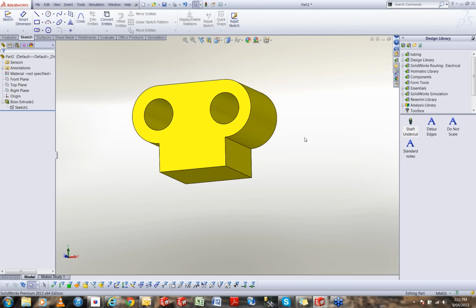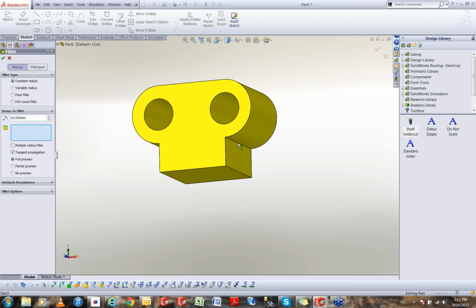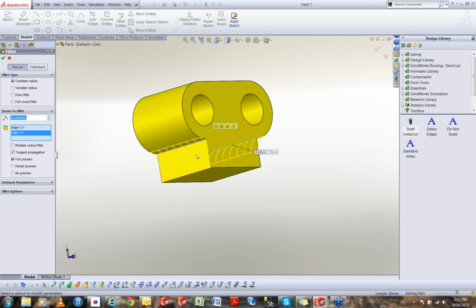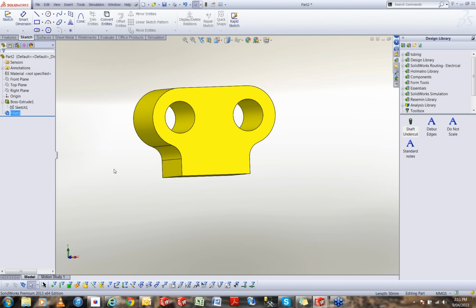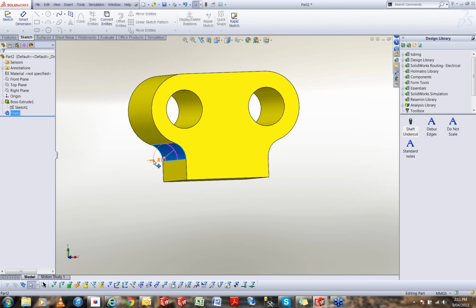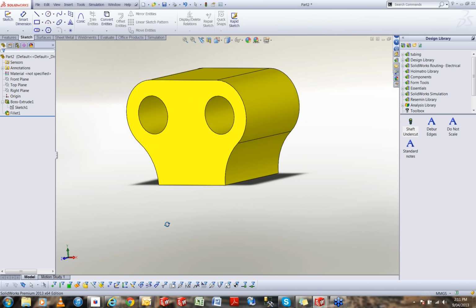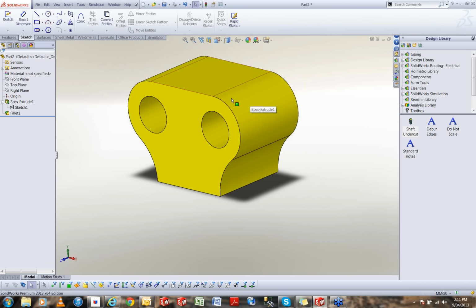So we've got a fairly sharp corner here where the circular face meets this flat face. So we might need to add a couple of fillets. So I'll start up the fillet tool, and all I have to do is just select the edges. I can set my fillet radius or leave it at the default, and I see the preview of those fillets there. I'll click OK, and I'll add those fillets. With SolidWorks, it's really easy to make changes on the fly. So I can simply select those fillets, and where I've got that 10 millimeter dimension, I can simply drag that out and dynamically change the size of my fillets and get a good idea of what consequences that's going to have on the rest of my design. So I'm going to drag those fillets out to be 30 millimeter radius.